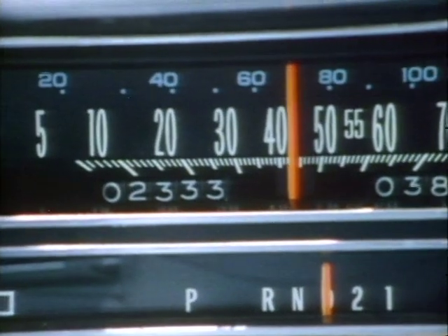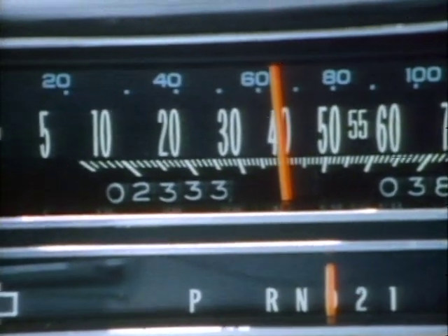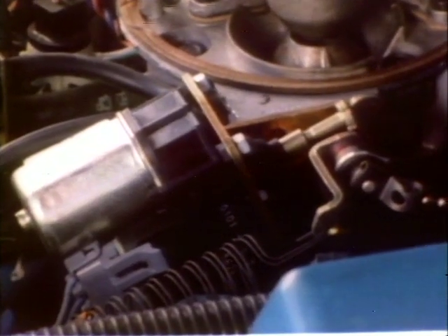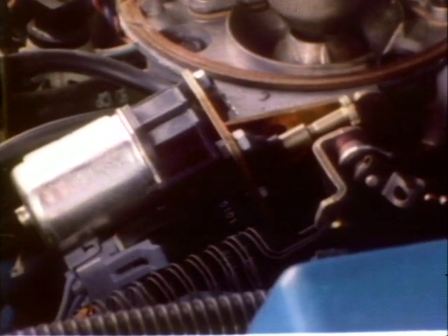When this occurs, the engine, which is still operating at a speed above idle, can emit a high amount of exhaust emissions due to this rich air-fuel mixture entering combustion. If the throttle is held partially open, sufficient air can then enter the engine to provide a lean air-fuel mixture. The ISC actuator provides this throttle opening by extending the plunger, partially opening the throttle.